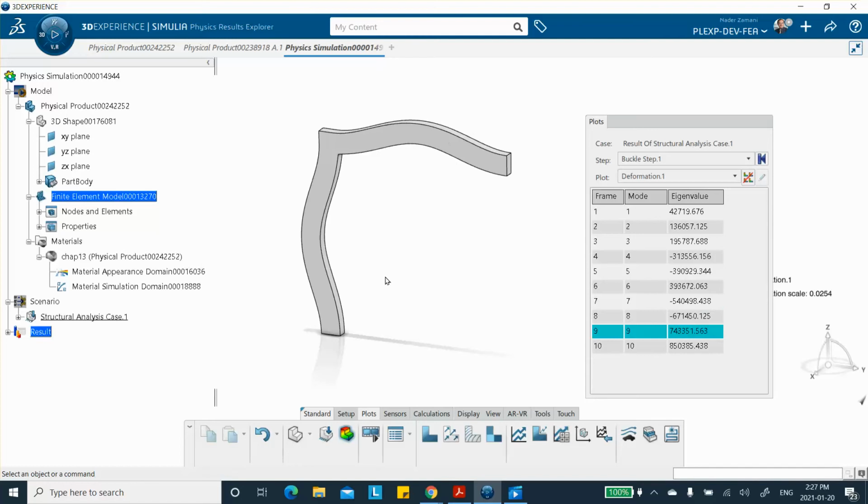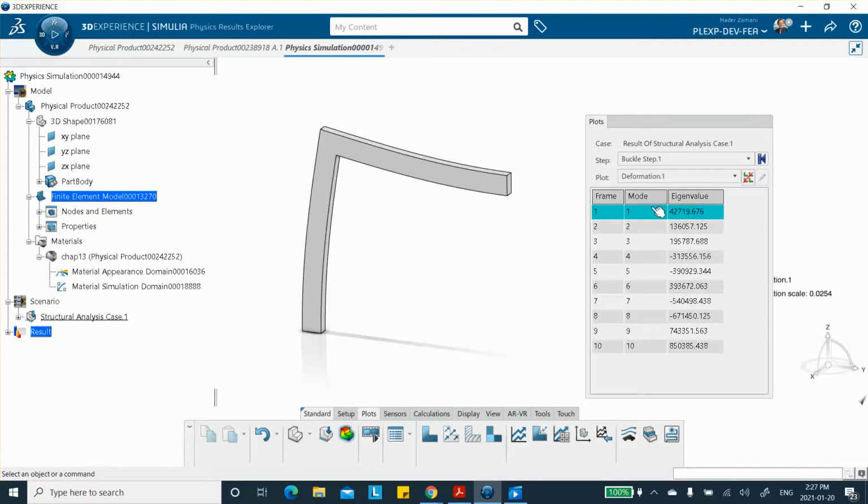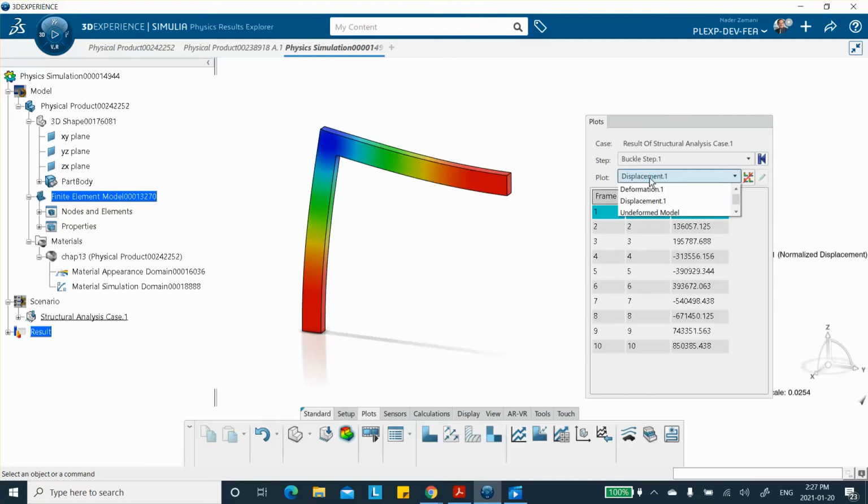This one is okay, but it's going to be very difficult to create this buckling mode. The one that usually happens is this, and then pretty much after that, in many cases, it's going to collapse, for beams and frames and things like that. Okay, that's pretty much it. You can also plot the displacement, which is really meaningless. And obviously stresses are totally useless. All right, folks. So good luck. We did this problem, and you're on your own.